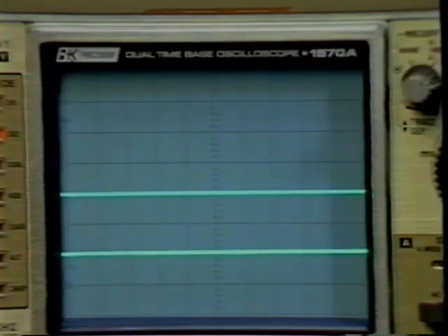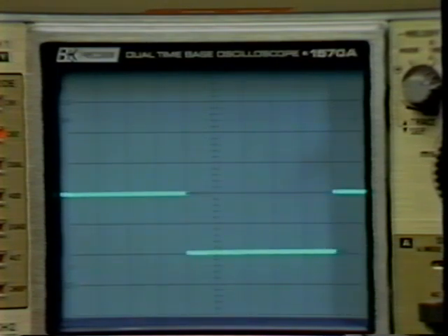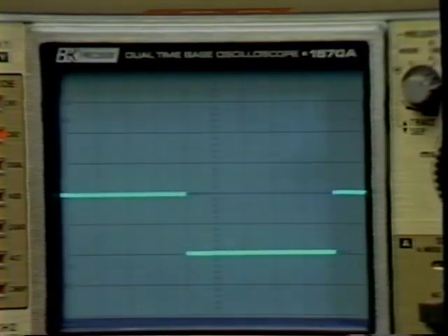Another feature of an oscilloscope is its trigger bandwidth. This specification is not usually printed on the scope, but is listed in its documentation. Trigger bandwidth refers to the scope's ability to capture quick pulses to use as a trigger. If a pulse is faster than the trigger bandwidth of the scope, it cannot be used as a trigger input. Keeping in mind these limitations, you are now ready to actually observe signals.